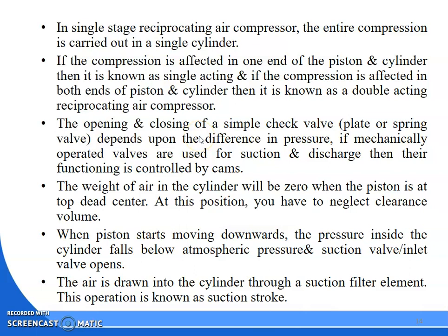And if the compression is effected on both ends of the piston cylinder, that is known as double acting. Here the opening and closing of the simple check valves, or that is your valves, will be operated by what? By the function of the pressure, or you can say due to the pressure difference. The weight of the air in the cylinder will be 0 when the piston is at top dead center, the position where we are neglecting what? We are neglecting the clearance volume.